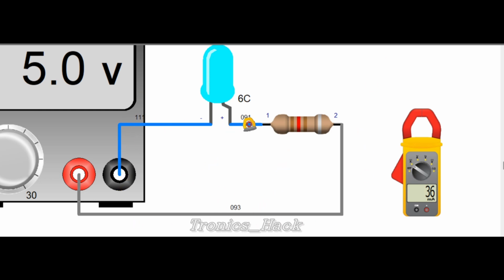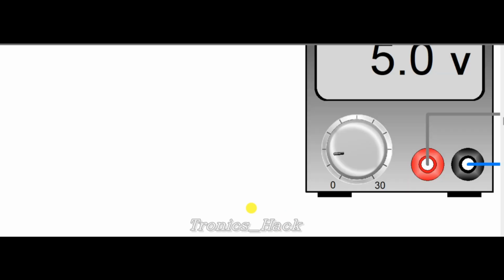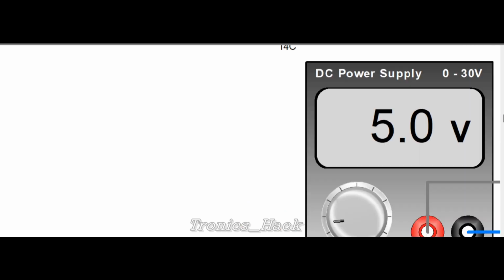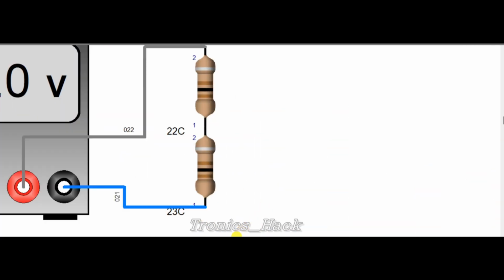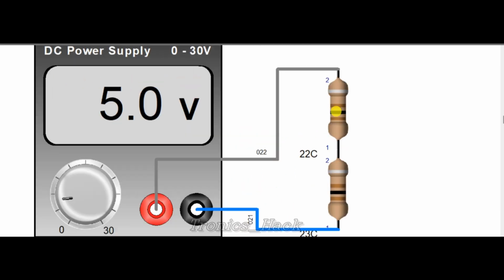Yeah, so now let us go to the current divider and voltage divider systems. We call this configuration the voltage divider. We put 2 resistors in series. If you put 2 identical resistors in series and hook up with the voltage, we divide the voltage in 2. The formula says that. Let me give you another formula.